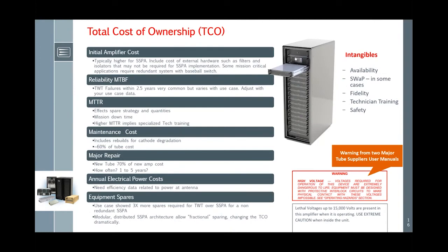So yeah, let's talk about the total cost of ownership. I've got a couple slides. There's a graphical model on the next slide. But the major elements here are the initial amplifier costs, the solid state PAs, often higher in cost than the TWT, that's for sure. Reliability is the next major cost driver over the lifetime ownership of the PA. And solid state has a clear demonstrated advantage again. But again, let me remind you, the architecture of solid state matters in terms of extending its effective MTBF.